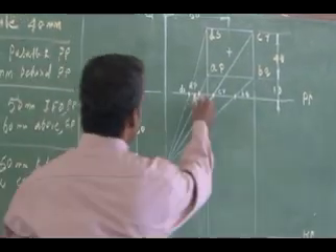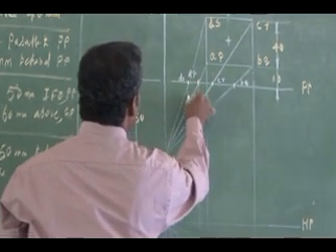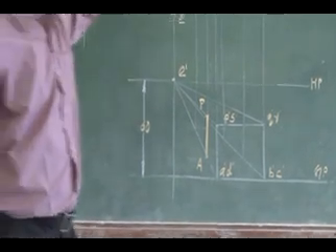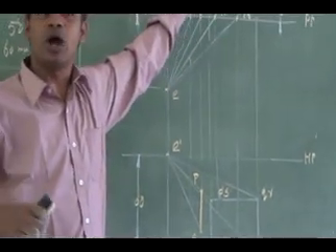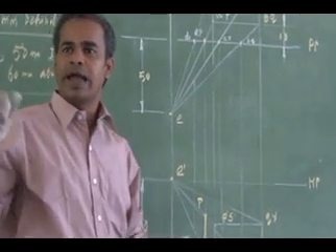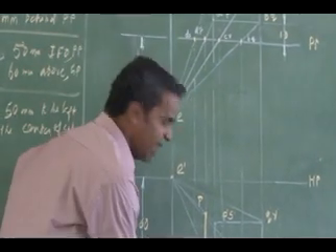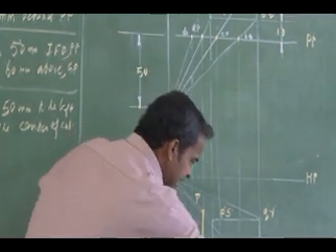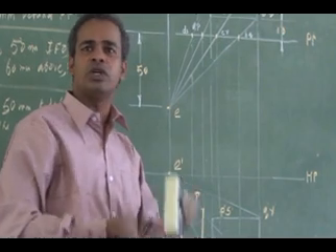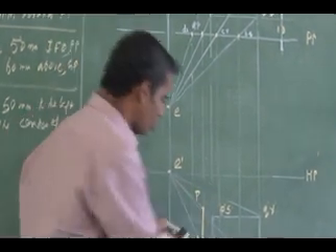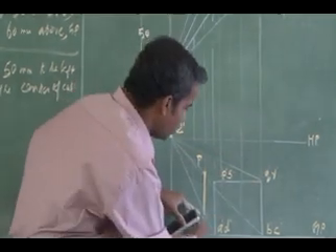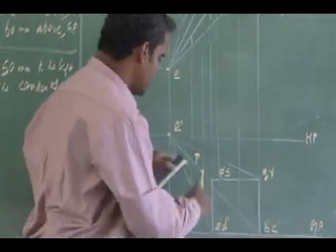Since the face is parallel, in your perspective also these corners should be parallel. So you should carefully use your drafter. Suppose I have A, then B has to be exactly horizontal. If you project wrongly, using your drafter in a tilted manner, you won't get the exact location. Since the face is parallel, A and B will be on the same horizontal line.